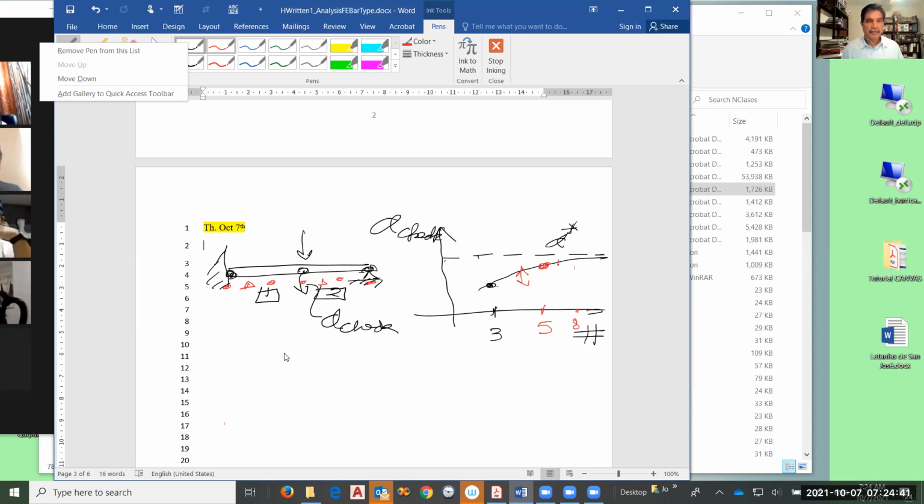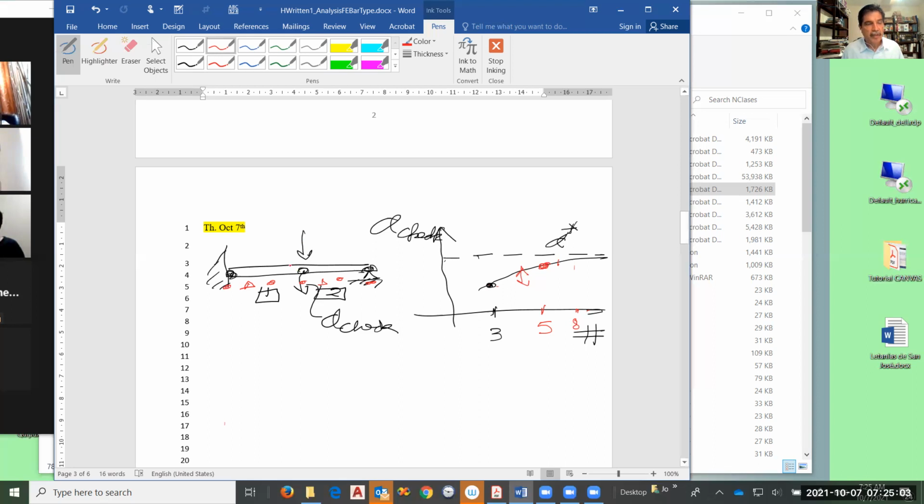We will see that in a minute, but it is possible that you make a partition, and in that case, these external forces do not coincide with the joint. But the best way to do it is, yes, make it coincide. So you have a joint at the point where you are going to apply a force. So in general, we try to make it coincide. But you could analyze, for example, let me, this is an extreme. I don't suggest to do it, but you can do it.